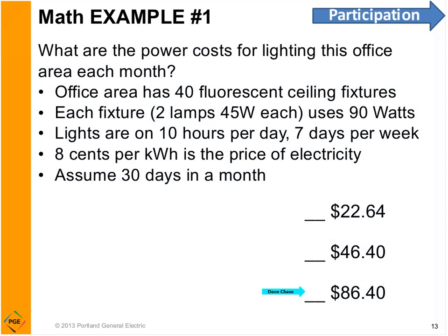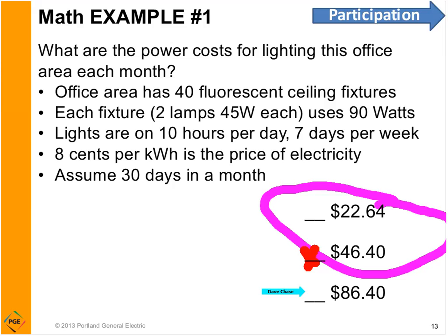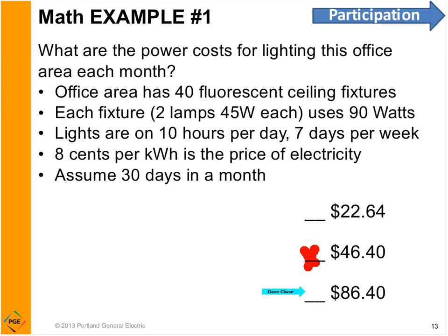Other projects I've seen while you're doing that are, again, if I'm adding equipment to my facility and you're adding lines and circuits, the electrician may come to you and say, we're out of space in the panel. I need more amps room in the service. And they have found that by changing out lighting and doing energy efficiency projects, they reduce their energy, which reduces their amps, frees up space, and can be a very effective way of avoiding installation costs that are amp related.